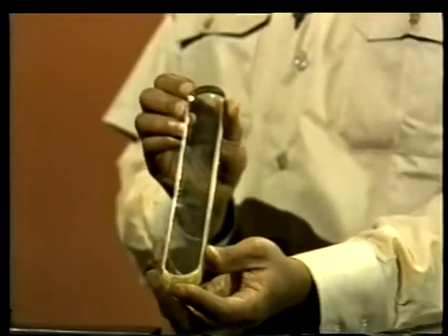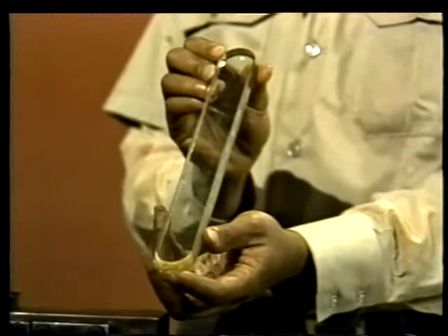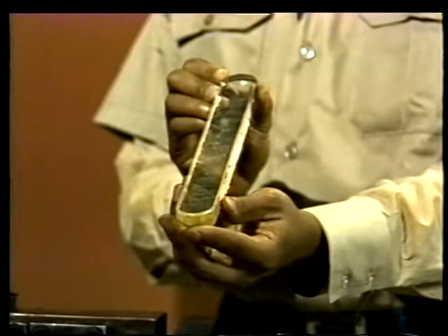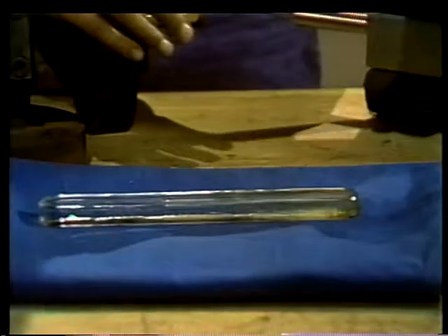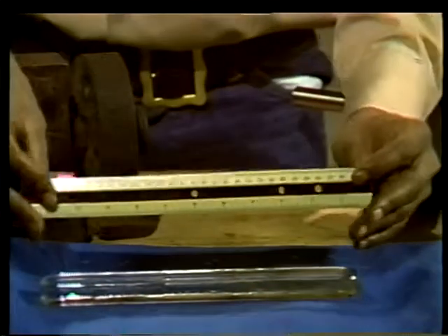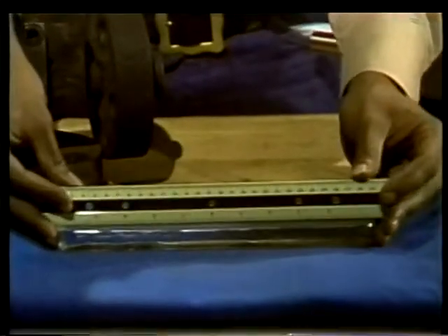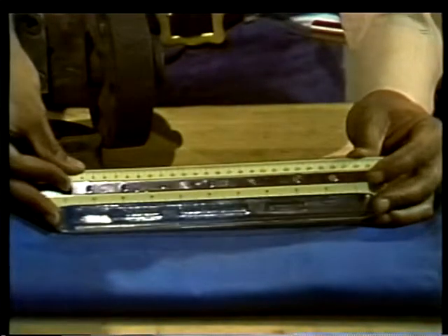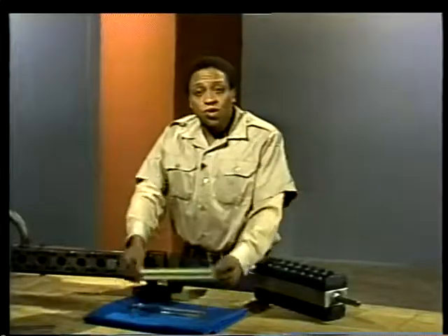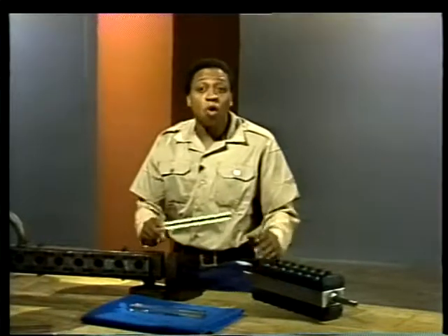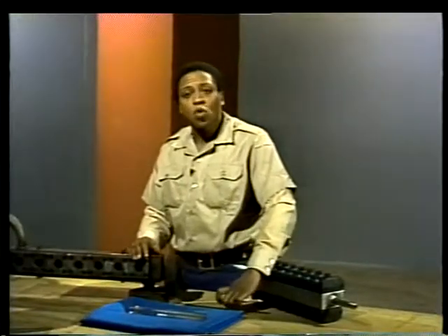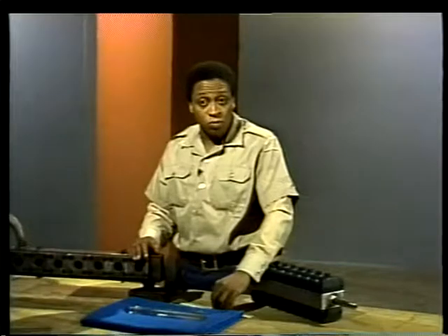Check for erosion by holding the glass up to a light and examining its surface for irregularities. Or you can use a plastic or wooden straight edge to determine if the glass's inside surface is flat. A glass with scratches, lack of clarity, or erosion must be thrown out and replaced by a new one. Old gaskets and cushions must also be replaced.